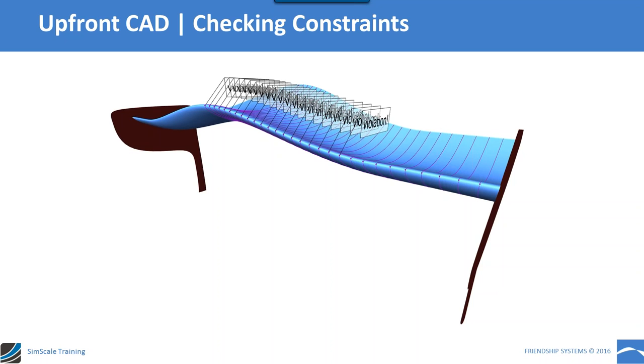The idea is to put some functions to describe, for example, that this point in the leading edge needs to be always lower than a value, or maybe you can also create a box, and when the geometry intersects with the box, you can say that this model is not legal, and you can test it later in CFD.